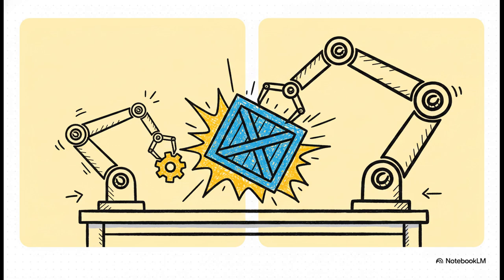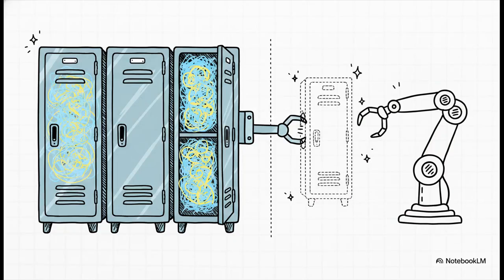It's literally just two totally unrelated tasks accidentally being assigned to the exact same workbench. If an older instruction takes a really long time, a newer, faster instruction might accidentally overwrite its workbench before the old guy is even done. It's a mess. So, the absolutely crucial point here is how we solve this mess, and the answer is register renaming.